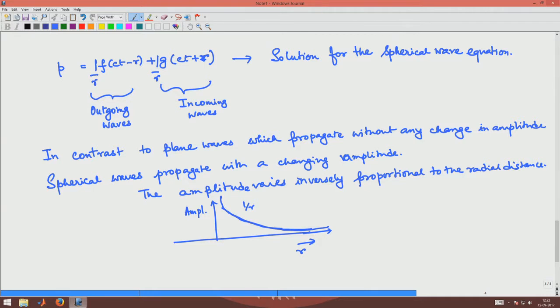So, in terms of plane waves, what we understood was that, the amplitude being constant, we had to put in a muffler such that we get some reduction of the amplitude at the point where the exhaust is opening out to the atmosphere. But in the case of spherical waves, as the wave is spreading and going to farther distances, the wave itself suffers a drop in amplitude.